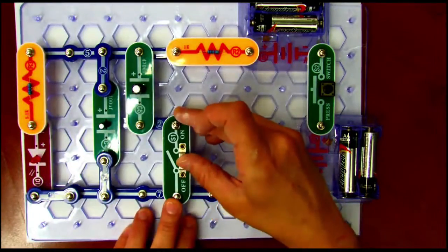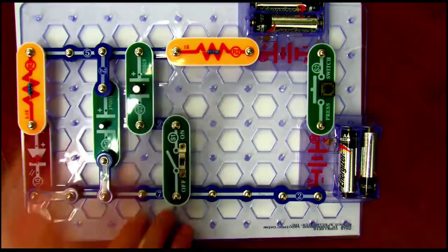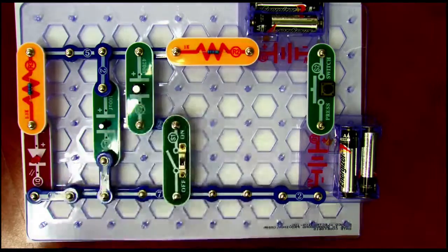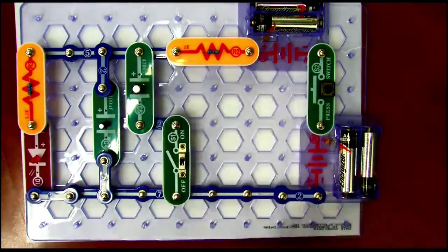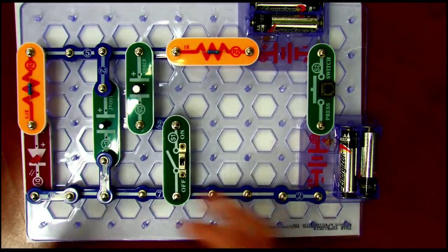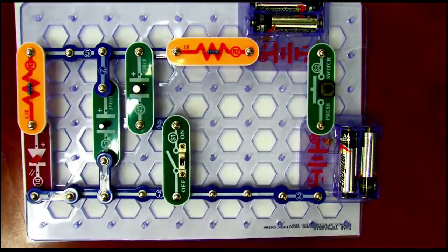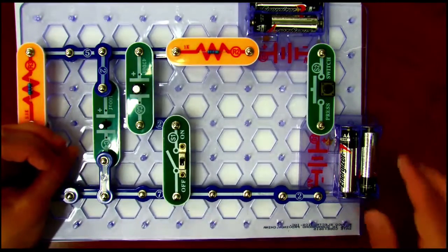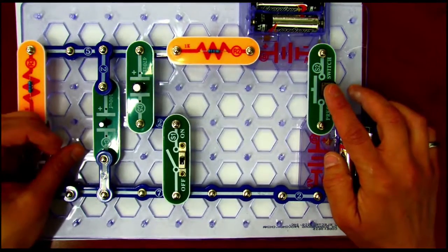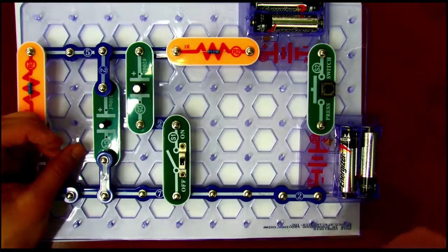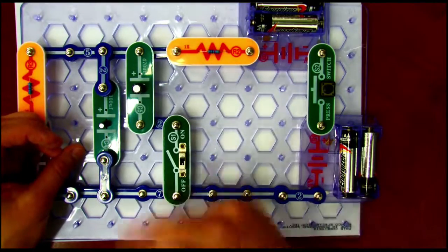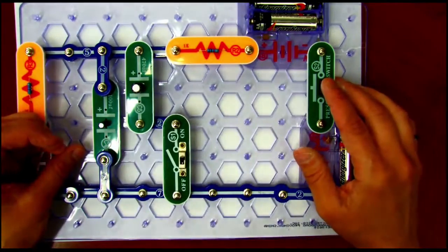I'm going to turn this switch on. So these are both now parallel capacitors. In parallel, you straight add. So 470 microfarads plus 100 microfarads, we're going to have more energy stored in the electric fields inside these little capacitors to use for the light bulb. So if I turn the switch, while they're discharging, it should last longer than it did when just the 100 microfarad one was there.